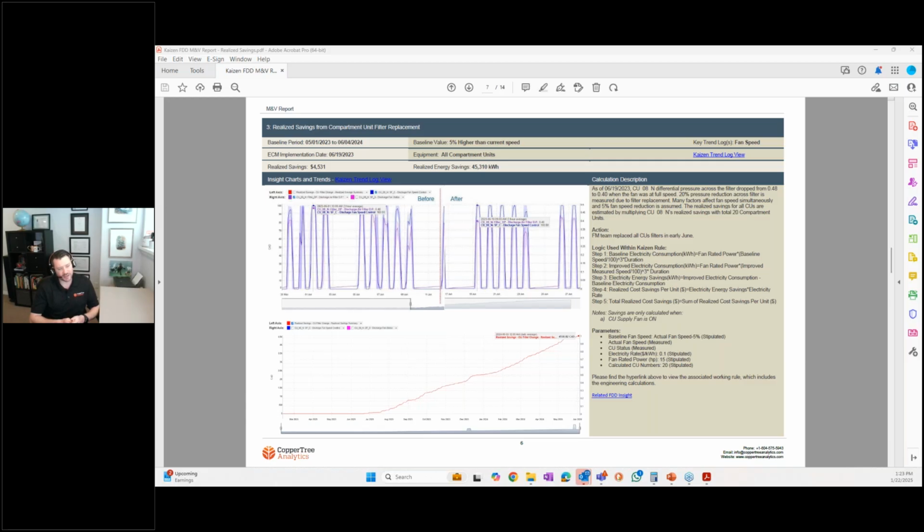Especially because for ASO, if what you're asking about is VAV boxes, usually we're reading from the VAV. So let me rephrase my answer. For ASO, we're optimizing the primary equipment, and we'd be using output data read from the VAV controller, not writing to it. So I would suspect we would have the value, like the damper position, for instance. That's usually what we would use for the demand calculation, so we would probably still be able to read that. Then we would do the optimization using ASO down at the primary equipment. So I think so, but I'll take that offline anyhow and find out for you, Ryan.